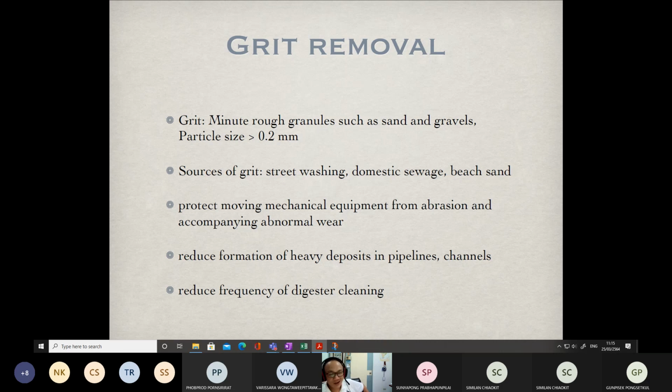In fact, why do we need to have the digester? The digester is actually the reactor that carries out the anaerobic process, anaerobic digestion. The anaerobic digestion normally yields methane and carbon dioxide, which we generally call biogas, especially the methane. It is the only gas produced from the biological process that actually has calorific value, so we can use this methane gas as an energy source for several purposes.